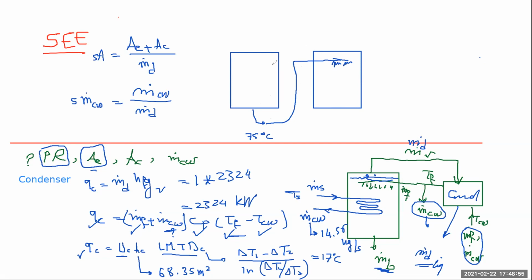It's easy. What you can do is take the vapor which is leaving here to condense. When it condenses, you are going to get it as a product, and you are actually generating an additional amount of vapor here. You take this amount of vapor into another effect and so on. And whatever is going to be rejected from here is going to go to another effect and so on.